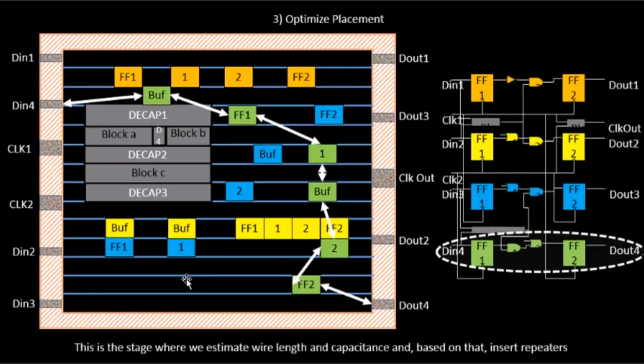Okay, so next we have to check whether what we have done is correct or not. Since the clocks are not built, we just check the data path over here, considering the clocks are ideal. By ideal clocks we mean that the time required for the clock to reach flip-flop 1, flip-flop 2, any of the flip-flops is 0.